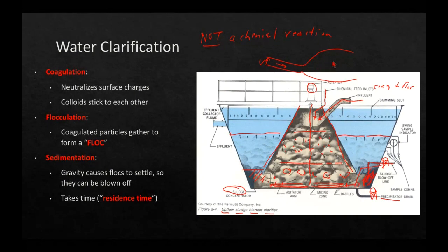And then when that water enters into the lake, the velocity slows tremendously, and it no longer has the energy to carry the larger suspended matter. So whenever we see a converging nozzle or any sort of a convergence of fluid, we see its velocity is going to drop. And in the case of this here with suspended matter, the suspended matter will drop out, the heavier stuff. So notice we've got the converging cone shape, and the reason there's a converging cone is to slow down the water as it travels through the clarifier.